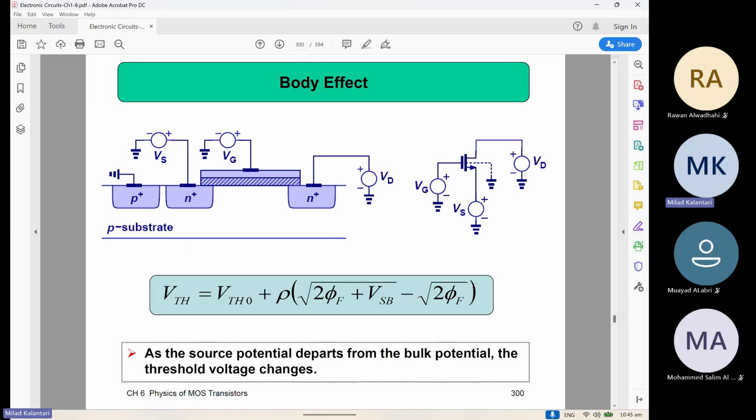One other thing that this MOSFET device has is, you had this three terminal device, right, which we were showing initially, but in fact the substrate itself has some connection and needs to be biased. The substrate is p-type for the n channel, and we have some contact point to bias the substrate to make sure that it's not floating.